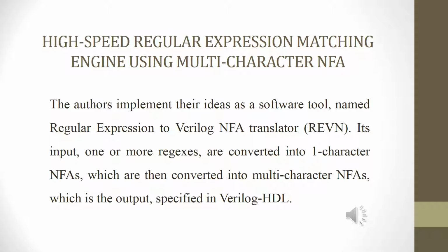The authors implement their ideas as a software tool named Regular Expression to Verilog NFA Translator. Its input, one or more regular expressions, is converted into one-character NFAs, which are then converted into multi-character NFAs, which is the output specified in Verilog HDL.